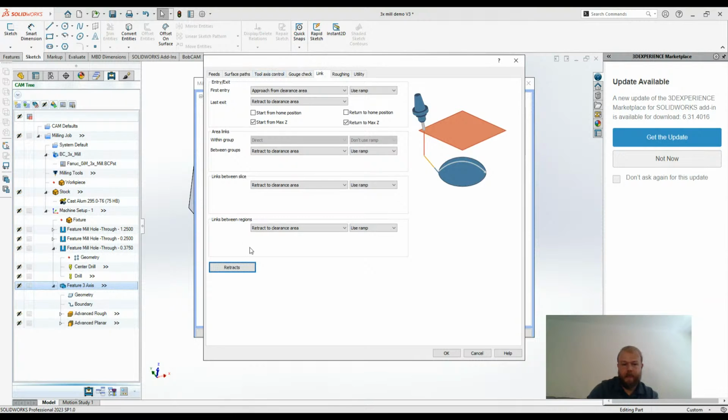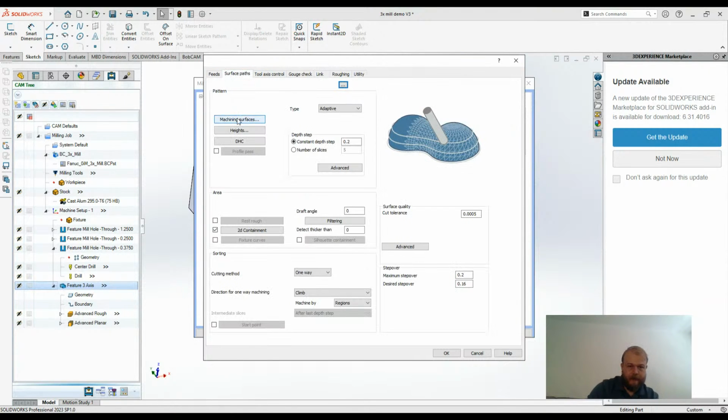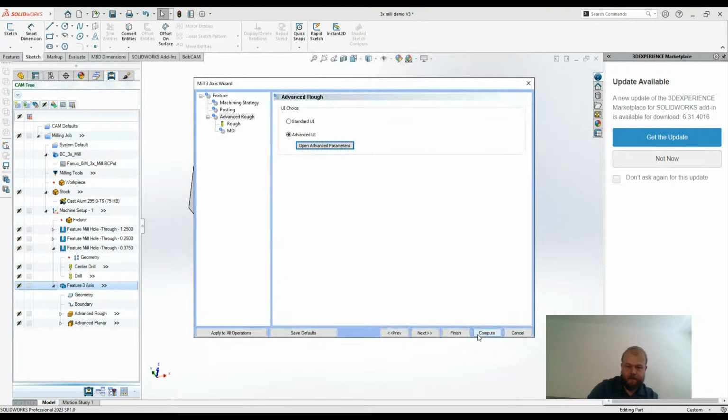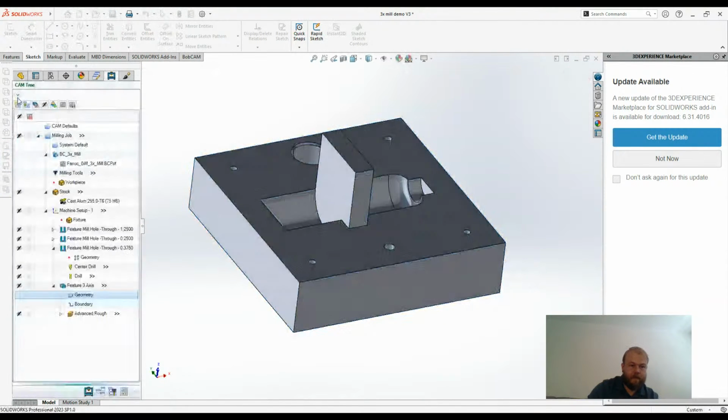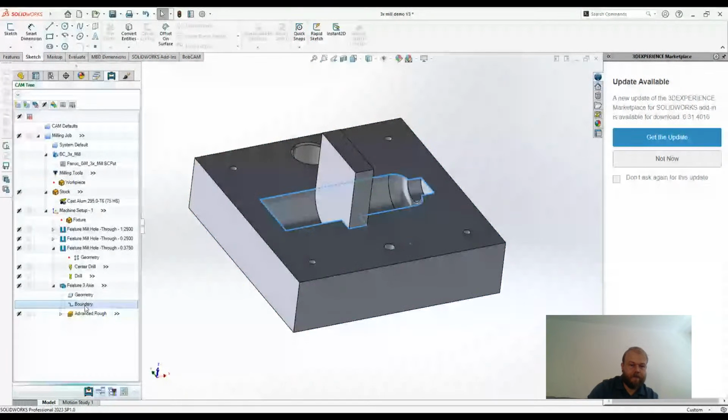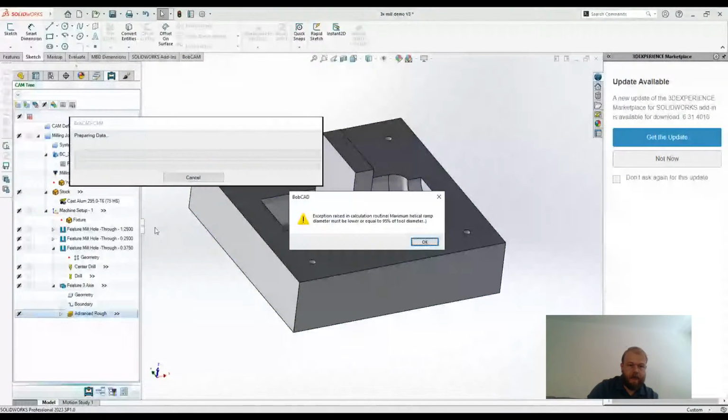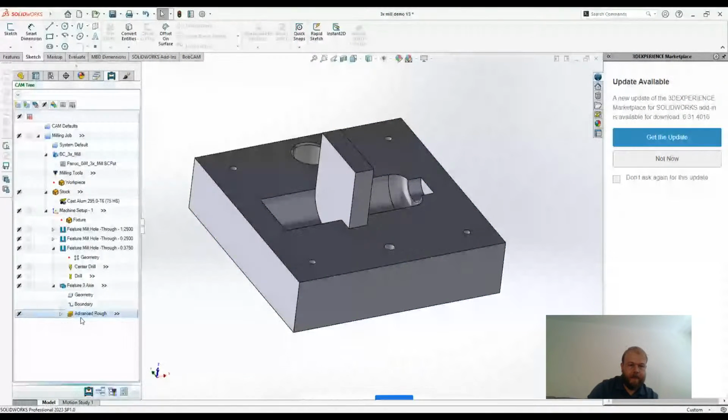Well, basically, in a pocket, there's going to be options where we're pocketing, and we will always go back to the top when we're pocketing. We are able to control that now and keep the tool down in our pocket operations, just like we integrated that option for profiling. Now you can do that.